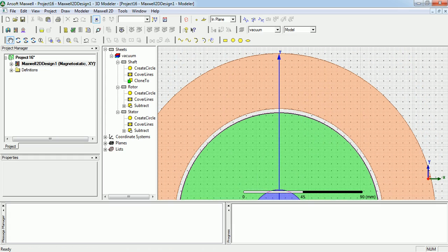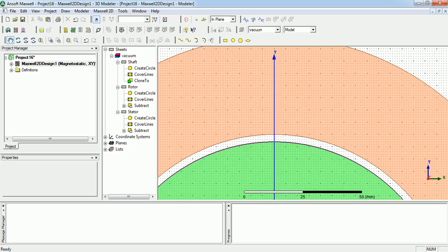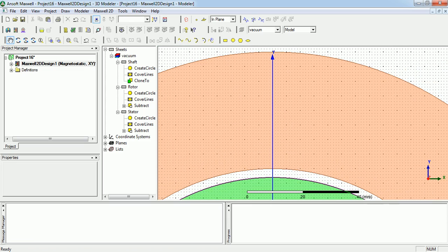Such that I'll be drawing the slot in this particular location. The reason again is I can navigate, I can measure only in the X and Y directions. So I have chosen this particular slot so that I can easily navigate in the X and Y directions.